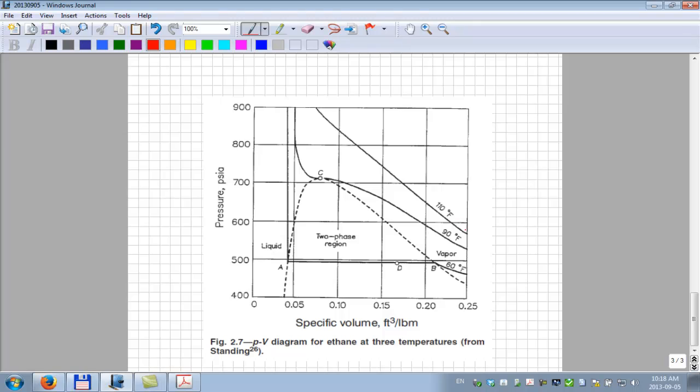You can see at the temperature of 90 degrees Fahrenheit, which is approximately the critical temperature of ethane, that the volume is coming down pretty much straight down here, and then it turns the corner, becomes more or less flat at this point, the derivative, and then continues its track downwards towards behavior that's becoming more like ideal gas behavior out here at lower and lower pressures.